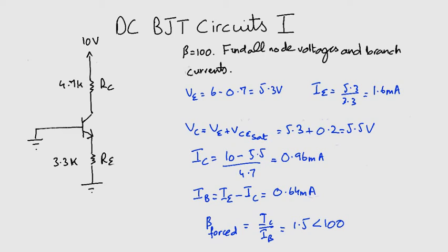Similarly, the collector base junction cannot conduct since the N-type collector is connected through RC to the positive power supply while the P-type base is at ground. Therefore, the collector current will be 0. So, the transistor is in cutoff. The emitter voltage will obviously be 0 because no current is flowing, and the collector voltage will be equal to 10 volts. Straightforward, yes? Now it's time for our quiz.